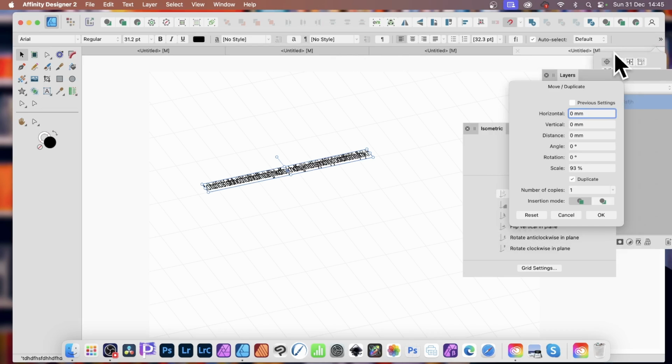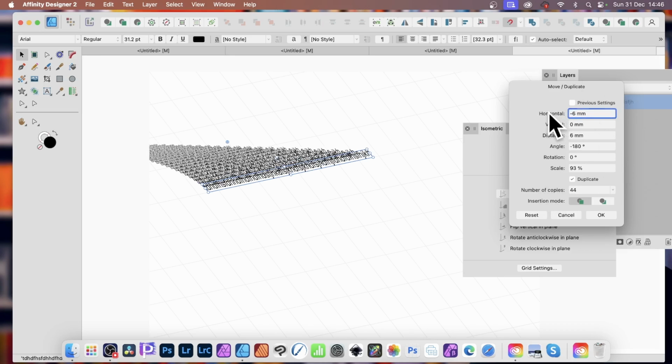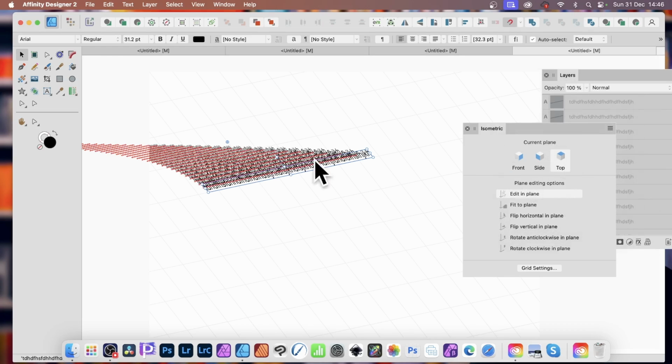But again, you can do the same with this option here. Let's just bring that up. Unfortunately, it's off the edge, so you just see it here. So again, enable transform. Now it's just hidden there, blue. It's very hard to see, but a little blue thing. You can move that, reposition it, increase the number of copies, and you can see it zooms there again. And you can also use horizontal or that way. And again, click OK.